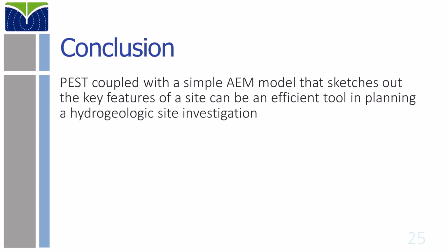So to summarize, AEM models can be constructed very simply and quickly to represent key site features that you want to parameterize if you intend to develop a groundwater flow model for your site. And they run fast. PEST can operate on those models to show you how well your planned field program will allow it to estimate the parameters you are seeking. And it will assist you in refining your field program to produce a focused and efficient work plan that will help to ensure the success of the project.